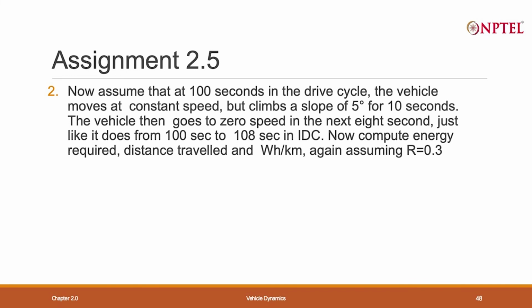You add that in your spreadsheet. Take a copy of that spreadsheet and add a few rows saying it is now climbing up. Add one more force, the gradient force. Nothing else changes. So, traction force is the previous 3 plus gradient force, and compute. This is a home assignment.